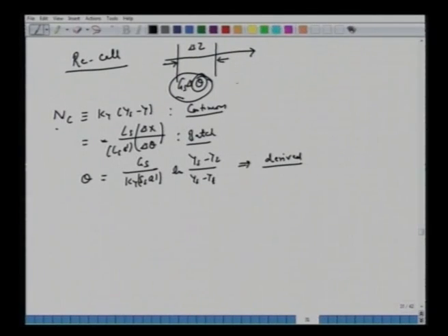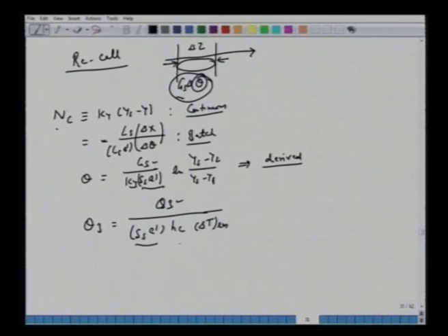Making the same analogy, that a certain batch of the solid is getting heated in this region, we have the time of heating theta 3 as Q3, the heating load, divided by Ss A prime, Hc, and del T LM, the logarithmic driving force, or temperature. So we have applied the same analogy from mass transfer to heat transfer to obtain theta 3 as approximately 2 minutes. Okay. So now, since we know this theta 3, we should move to region 2 or region 1 to see what calculation we can do.